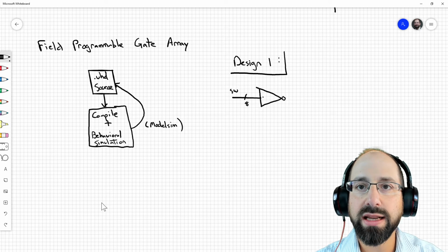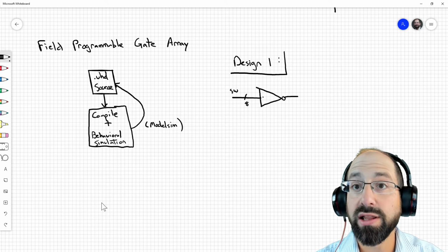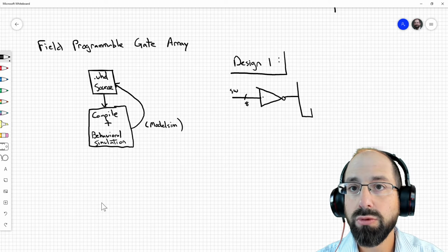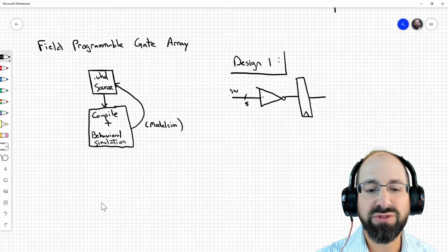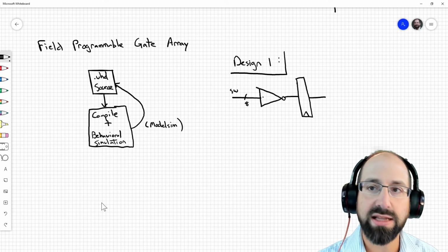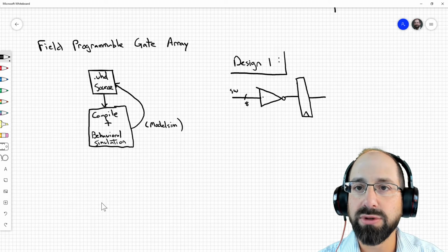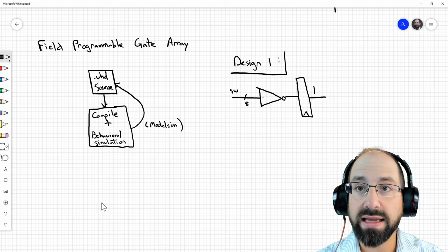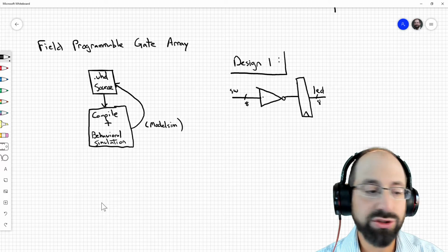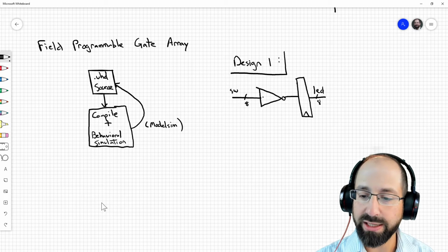And it's not just inverted, it's also inverting it and storing that result on the rising edge of the clock. As we've talked about when we were building our flip-flops and building our register files, we haven't talked about it that much in class, the syntactical connections to that. But when you have that rising edge of the clock, that is inferring a flip-flop. That is inferring some synchronous state storage. So there's our clock. We could label it clock if we wanted to. And then our actual output doesn't have any other signal name. We're directly mapping that to the LEDs, which is also an 8-bit signal. That would be my interpretation of what that code is doing.